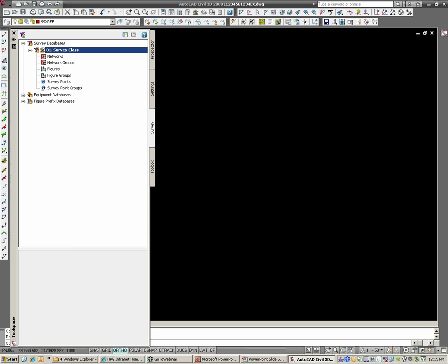Now, typically we're receiving our points. If we're going out and doing it, there's a number of ways. You usually have a CR5 file from the data collector, which is basically just a coordinate file in a different format. An RW5 file is not so much when you have GPS and you're collecting your points that way, but an RW5 is when you're going out there and traversing with a gun piece of equipment, and you have this recorded log.